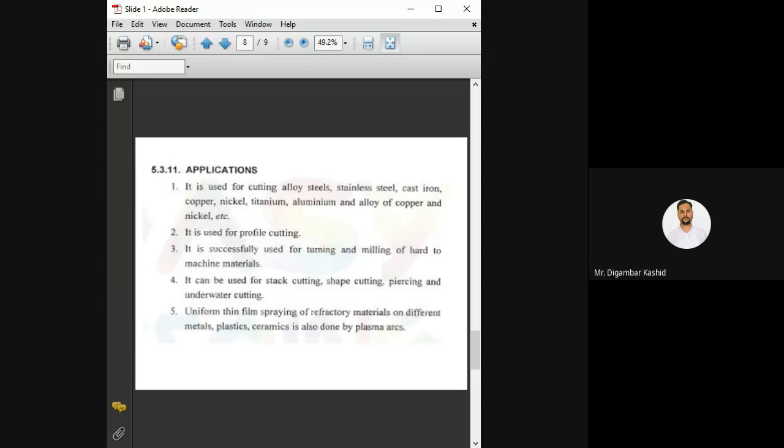Again, this process is commonly used for preparing ends of a pipe section before welding. To achieve a bevel cut on the end of your pipe, or the mouth of that pipe, the torch can be fixed at any angle, and you can rotate that pipe under that torch, so that you get that shape.